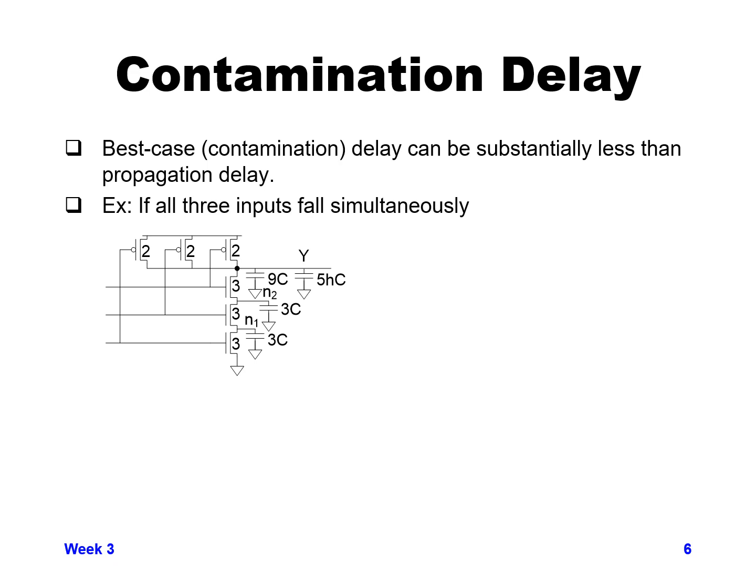For example, in this particular 3-input NAND gate, if all 3 inputs were high and all 3 inputs fall simultaneously, so that they're switching at the exact same time, that would cause all 3 PMOS devices to turn on at the same time, which greatly increases our drive strength pulling up to VDD.